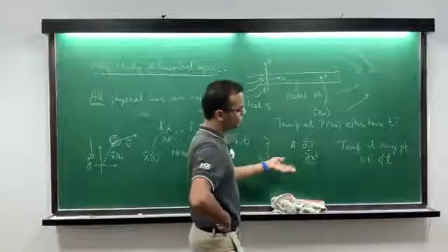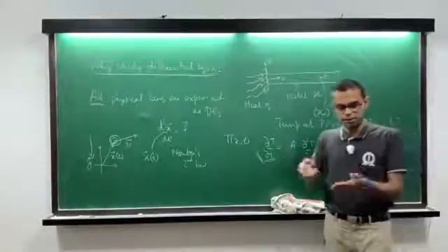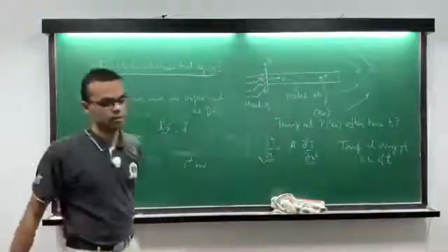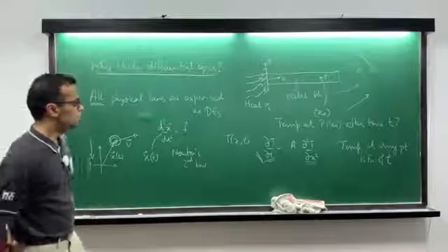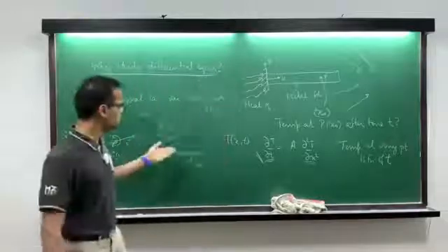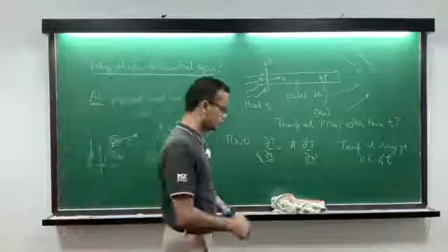And the other physical law, of course, is Fourier's law of heat conduction, which says that the heat flowing through any particular section is proportional to the temperature gradient across the section. If you combine those two, you will get this equation. Good. So again, to get the temperature field, you have to solve a differential equation. It's a little bit more complicated because it's a PDE, but it's still a differential equation.